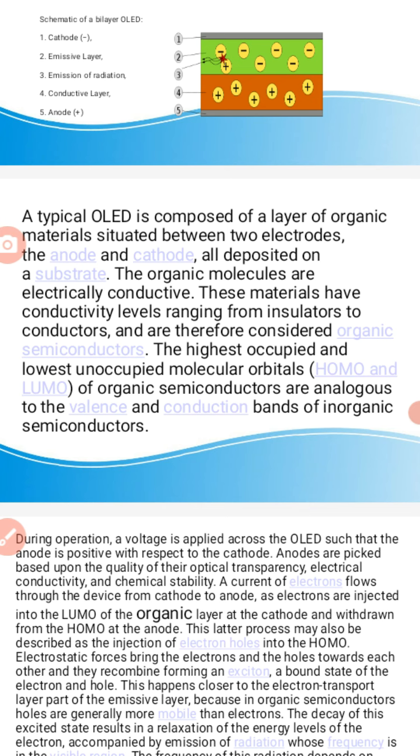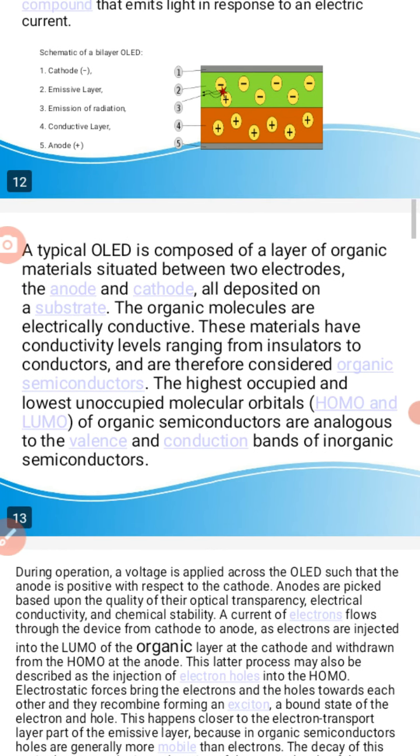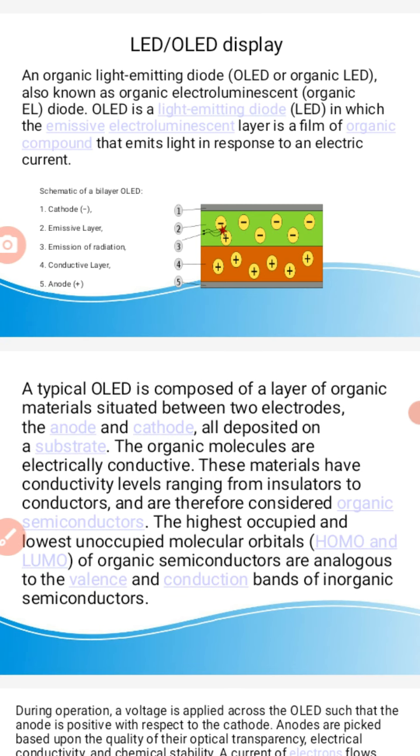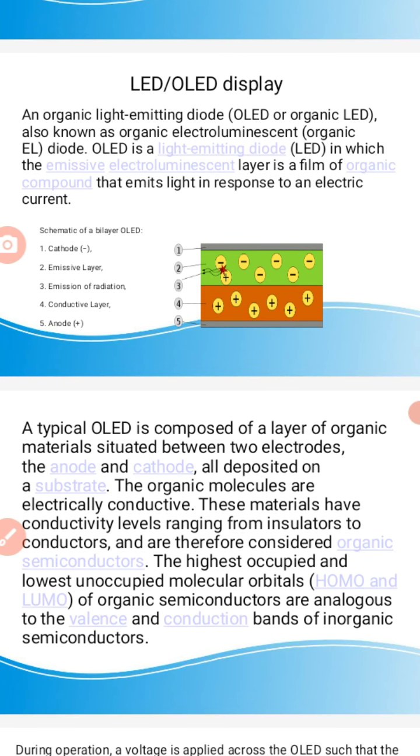However, when you connect these two slabs using electrical contacts and pass an electrical current through them, surplus electrons from the n-type slab flow and release photons from the p-type slab, which emits light. OLEDs work on the same principle, but they use organic molecules in lieu of n-type and p-type semiconductor materials to release holes and electrons.